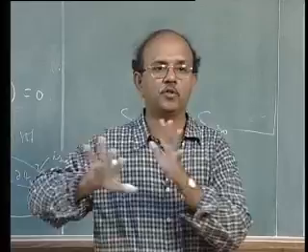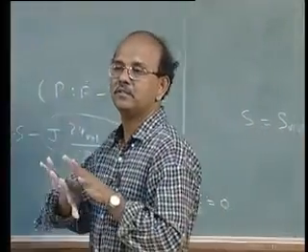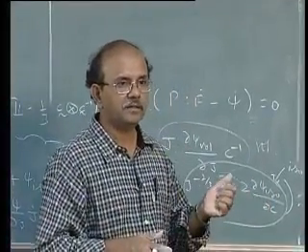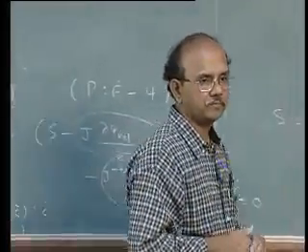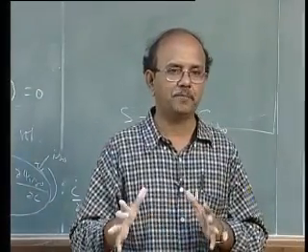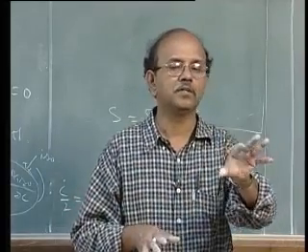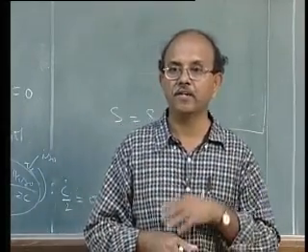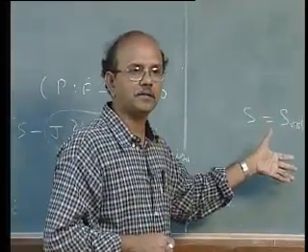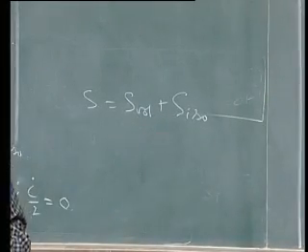Then when we came to compressible elasticity, what we have to do is to now distinguish between, or split this into, the volumetric part and the isochoric part. Then we again developed equations for S using the Clausius-Duhem inequality and realized ultimately that S itself has a volumetric part and an isochoric part.